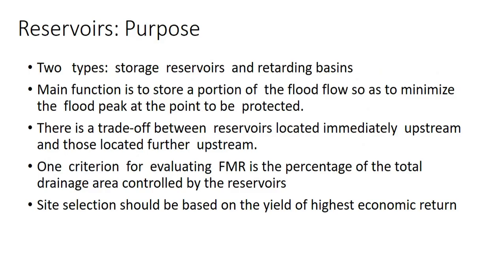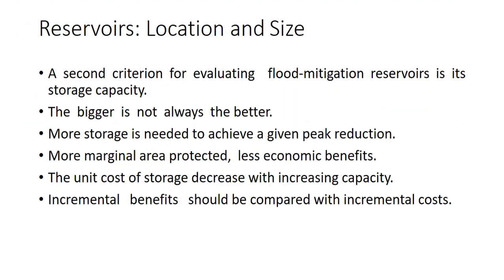Flood mitigation infrastructure are the following: reservoirs and your retarding basins to store a portion. These are also, class, your dams, no? Trade-off between reservoirs located immediately upstream and those located further upstream. The bigger is not always the better. Take note of that. The second criterion for evaluating a flood mitigation reservoir is its storage capacity.